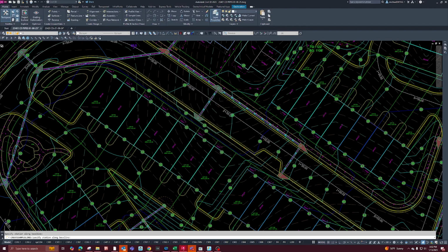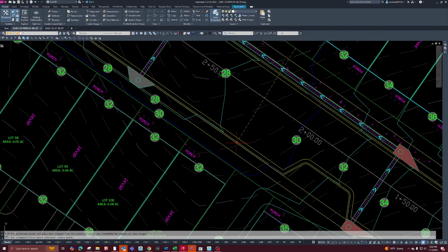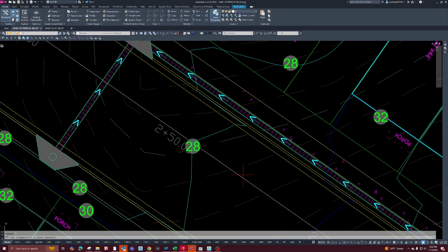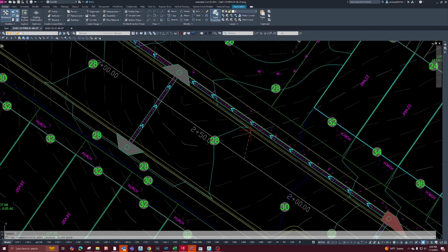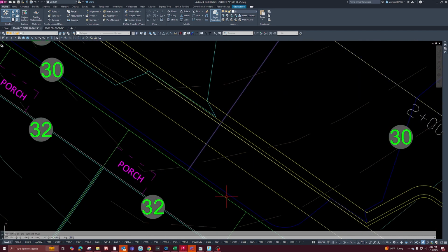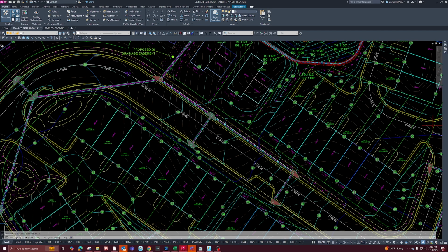I actually need to hit escape and check really quick. So from here to here, yeah, 57 feet. To the right, we have 25 feet, and this way we've got 32 feet. If we turn our corridor on, we can see it as well. CC Road Corridor.